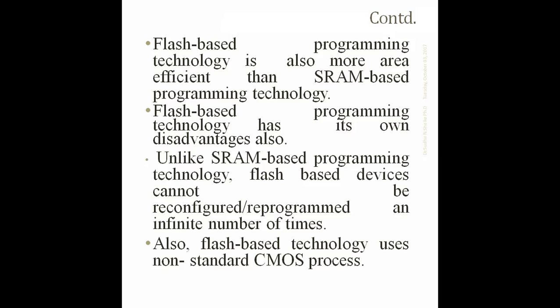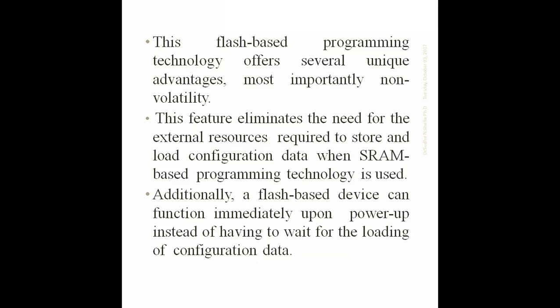Unlike SRAM-based program technology, flash-based technology cannot be reconfigured or reprogrammed an infinite number of times. Only a limited number of times it can be reprogrammed. It cannot be an infinite number of times. Another drawback of flash-based program technology is that it uses a non-standard CMOS process. It is not the standard CMOS-based technology.